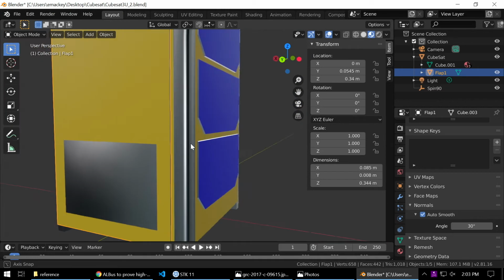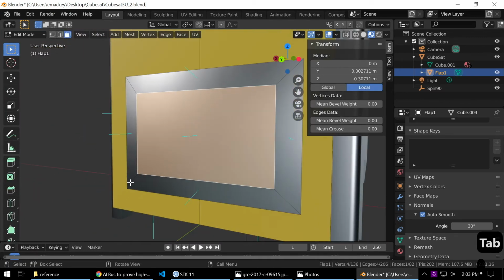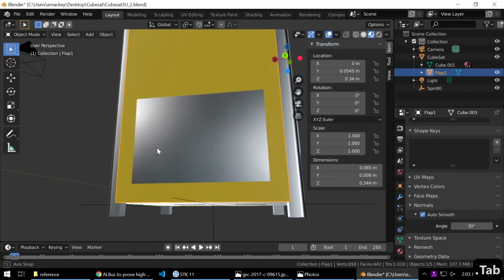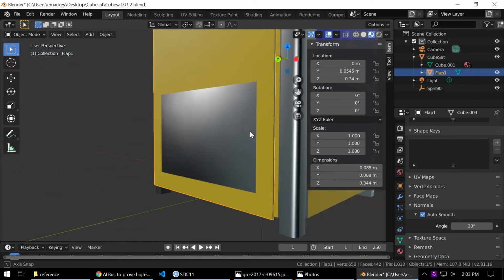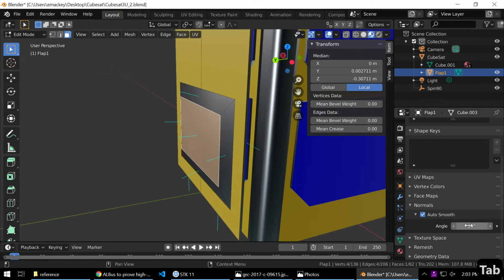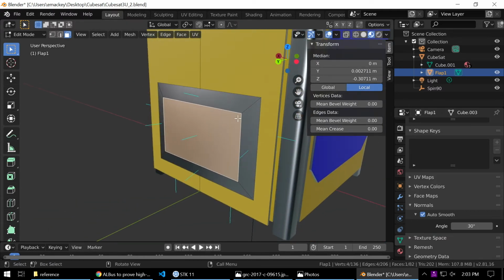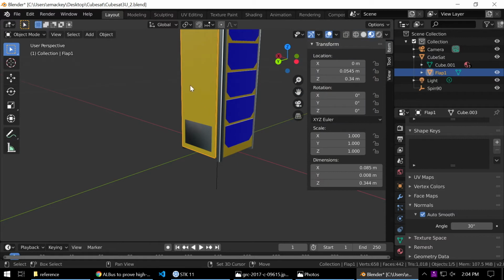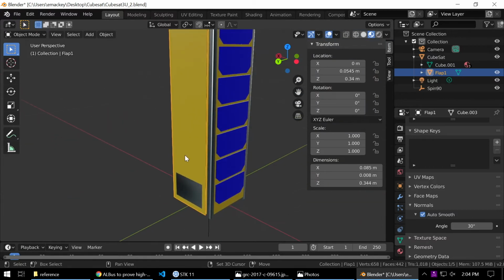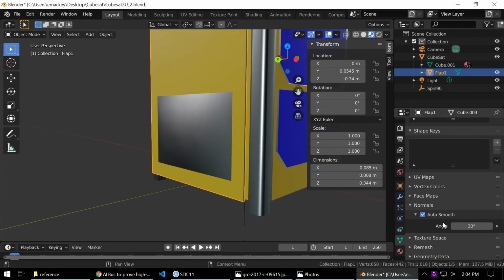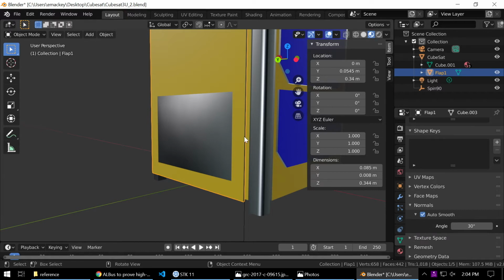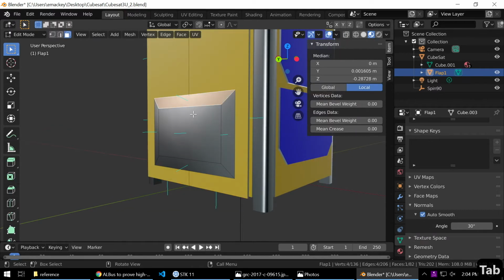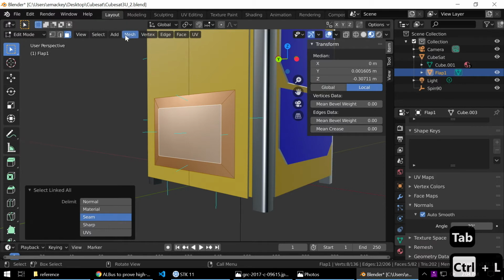But we have a problem down here now, where we created the pocket, as you called it. It too has become smooth shaded. And what's worse, its angles are so shallow that it would be hard for me to reduce this number enough to make these things into sharp edges without a number of other things becoming sharp as well. Our cylinder actually has steeper edges on it than this pocket does. So with that smooth angle, there's no more space between the shallowest sharp edge and the sharpest smooth edge. So what I'm going to do is select the pocket and mark it as sharp.